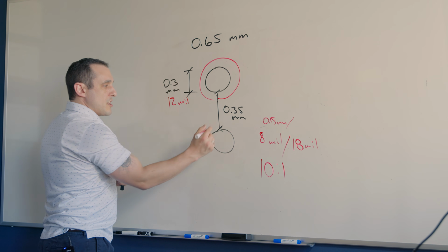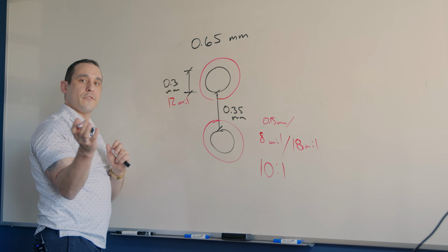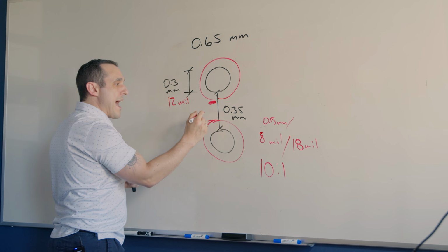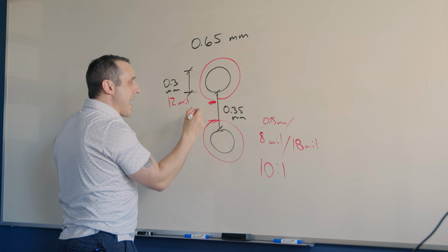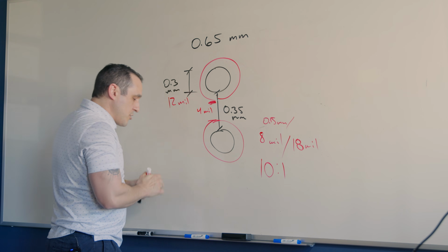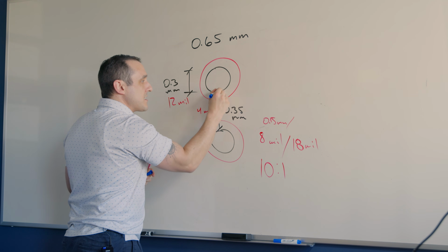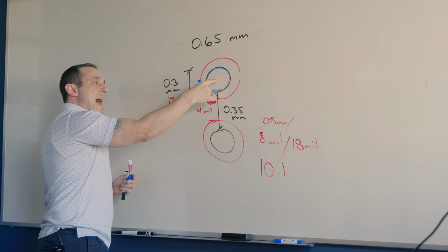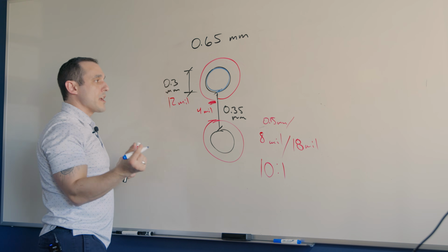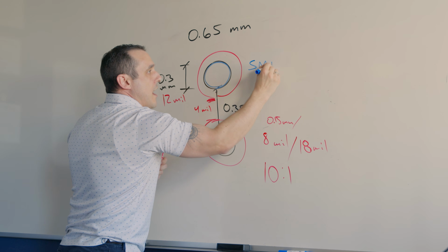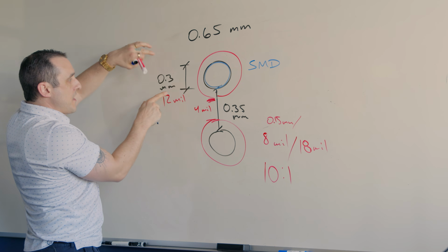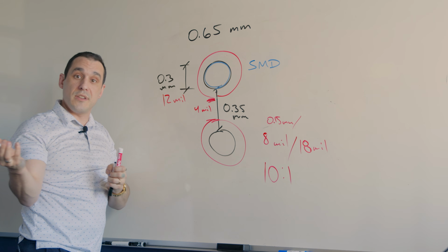Well, here in this situation, if we're putting these large pads that we're using for via in pad, we might end up having a smaller clearance right here between the copper pad edges. And that's okay. This copper pad edge clearance could be down as small as 4 mil if we need it to be. But what we would want to do is set the solder mask opening in this case to be equal to the pad size, or the copper amount that we need to expose to the bottom side of the BGA for soldering. So this is where we're using solder mask defined pads on these BGA pads, or on these via pads, in order to define the amount of exposed copper that will be given to the BGA during soldering.